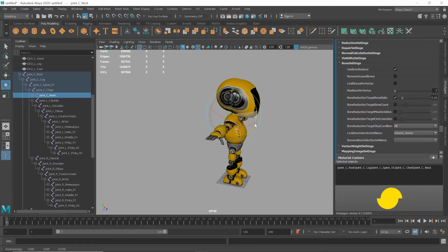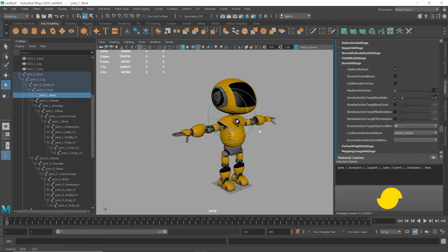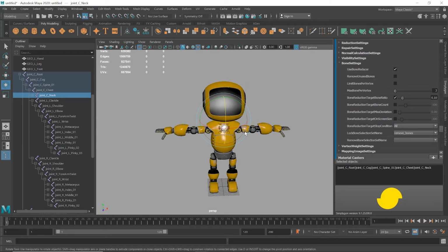One small piece of advice for Bone LOD in general: if you're going to remove a lot of bones, it's a good idea to have a bind pose that is similar to the standard pose in-game. If, for example, we use this T-pose as a bind pose but remove shoulder influence in one of our LODs, the arms would fly straight out like in this LOD. So do keep this in mind.